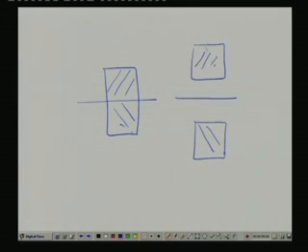Then what you are getting? Then we are getting the mass more away from the neutral axis. So, I just referred to this as a neutral axis. Once we go more and more away from the neutral axis, we thereby increase the I. Of course, y is also increased, but it does not matter, the overall value of I by y will increase. So, what we understand is that if we keep our materials much apart from the neutral axis, then we get a higher value of section modulus Z. Better means it will be better for the stress levels. So, that means the stresses in the machine members will decrease.